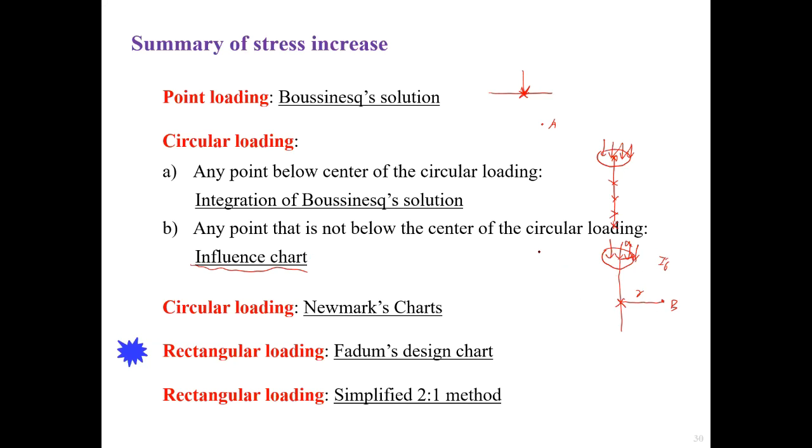So our stress increase, delta sigma ZZ, equals I sigma times q. So that's the second scenario. So 2 scenarios for circular loading. And then for circular loading, we have another method, which is called the Newmark's chart. So that's one.